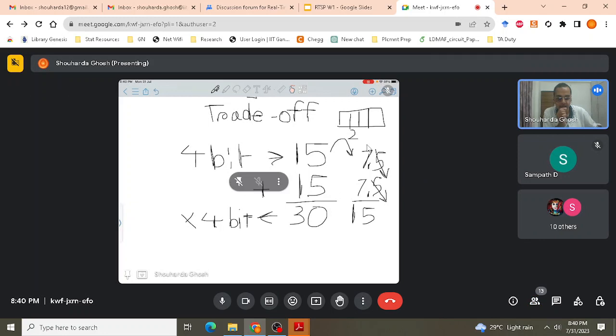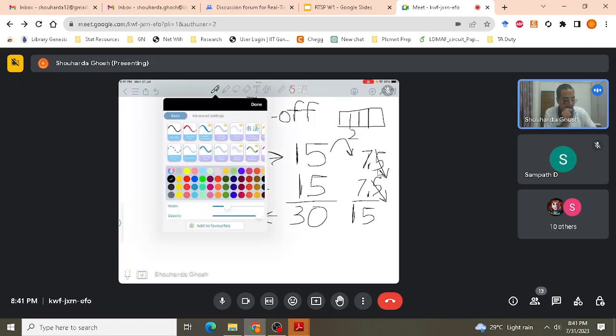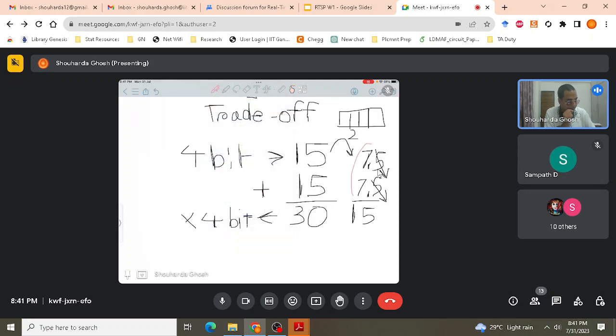So you are able to understand why I am not able to represent 0.5, what is happening over here? Yeah, we understood. Because I can represent only 4-bit integers over here. So when I am dividing by 2, I'll later tell you what the divide by 2 means in hardware. We cannot represent 7.5, it becomes 7. So rather than 7.5 plus 7.5, we actually end up with 7 plus 7, and that yields us a 14.